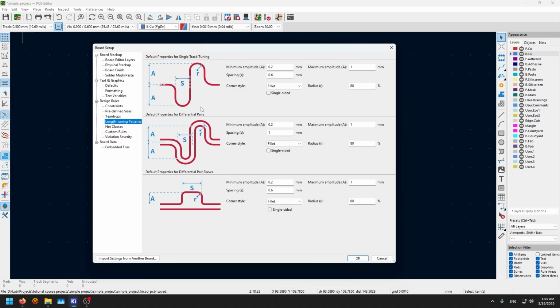Basically, you have many signals that must be time critical, meaning the time that they are getting out from the generating IC to the target IC, they are generated at the same time. But you as a designer need to make sure they arrive at the destination at the same time. This is really advanced, and it's getting required more and more these days. How can you make sure of that? Well, you're gonna do something called length tuning for single tracks and for differential pairs.